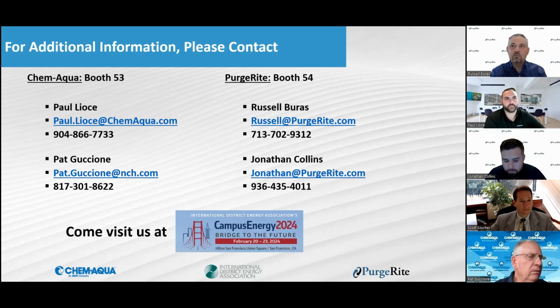There are times where things might get bypassed for a variety of reasons, but in general, you want to do all the big stuff, and then depending on what you're feeding from air handler units or other type of units, the best practice tends to be, once you get the mains cleaned and most of the branch lines, any large branch lines, if there's bypasses down those, you get that ready to go. And then one of your last steps is to open that up.